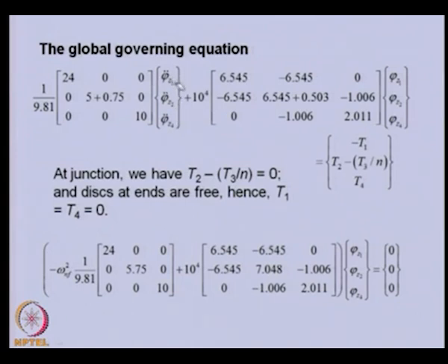So, you can see that 3 variables are there, and the first 2 correspond to element 1 and these 2 correspond to the second element. Similarly, this corresponds to the second element and these 4 are from the first element, and these are the torques at the common node, that is node 2, and at the junction this torque will cancel, because the reactive torques, once we assemble these elements, should cancel at the junction.